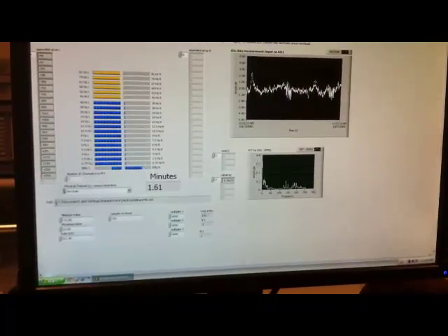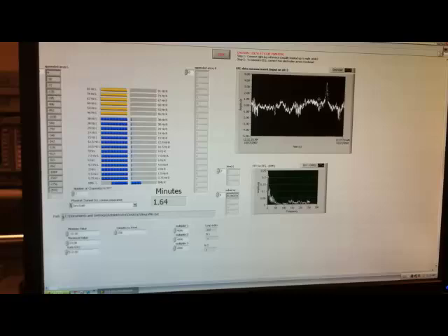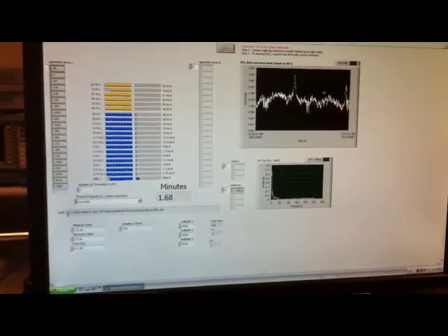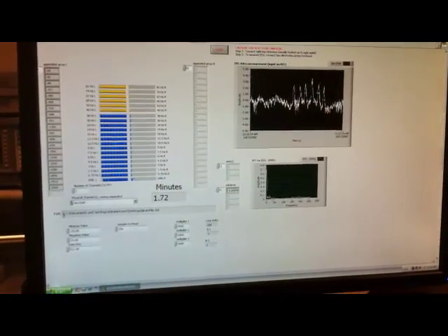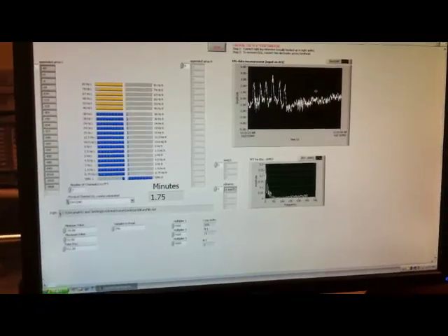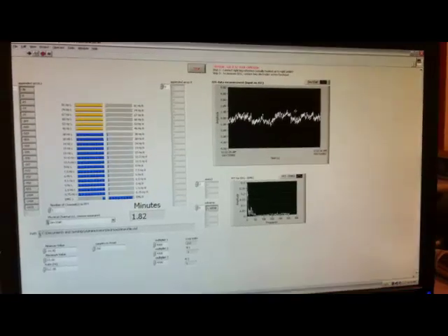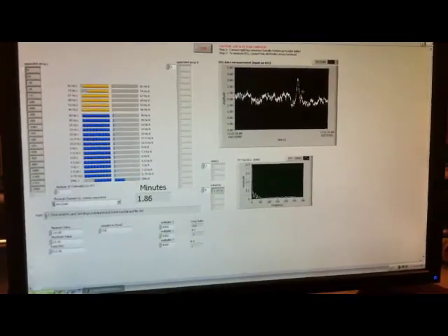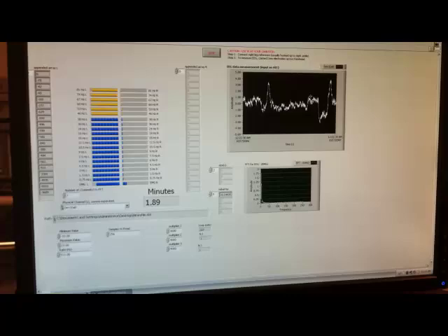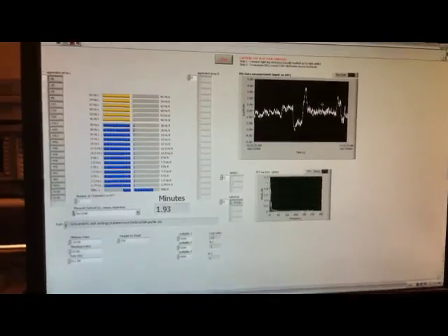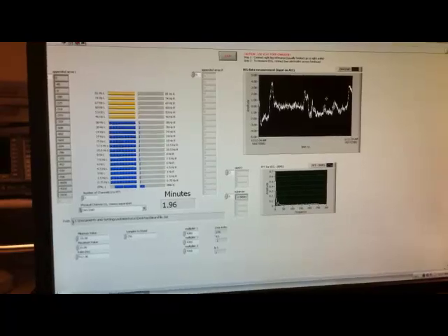So all this is doing is reading the EOG, but the point is you can see how much noise there is in the data. So it's me blinking. Well, the blink's pretty good. It's like 1, 2, 3, 4, 5, 6 blinks. But yeah, if you want to get EEG, you should not do it. For the ISCAS paper, we got it from the base of the occipital lobe. But do not try this on yourself.